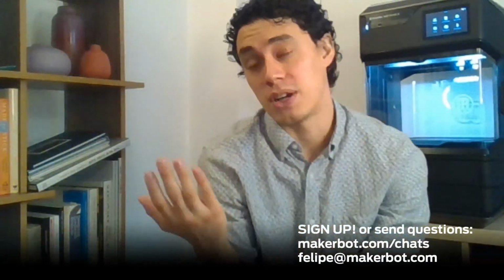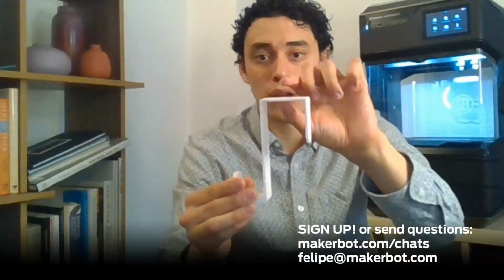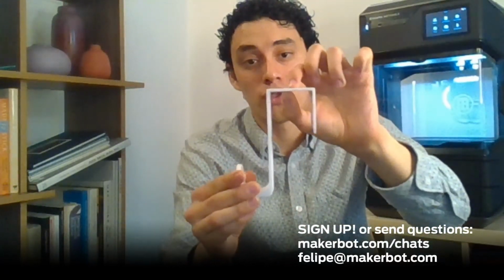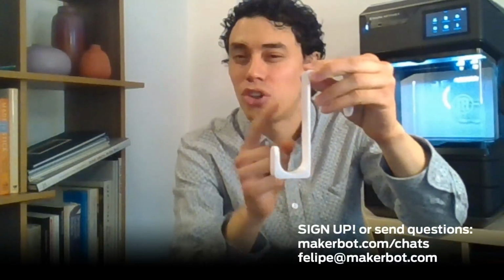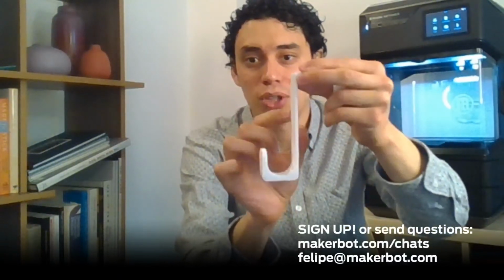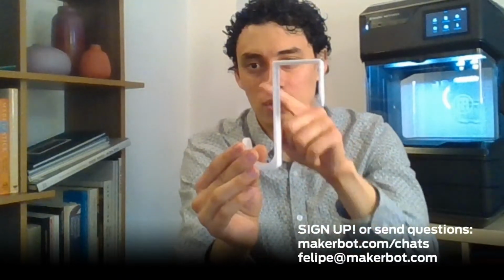And that's one of the things that we as designers, as engineers, always have to think about, right? What are my constraints? Which ones of them are set and which ones of them I can actually work with a little bit more. So in this case, the offset between the door and the door frame was set, right? This is a set constraint. The width of the door as well. However, this little guy here doesn't necessarily need to follow that same rule, right? Because if you can picture the imaginary door inside of the hook, this part no longer is prevented from being thicker as it gets out of that door frame, right?